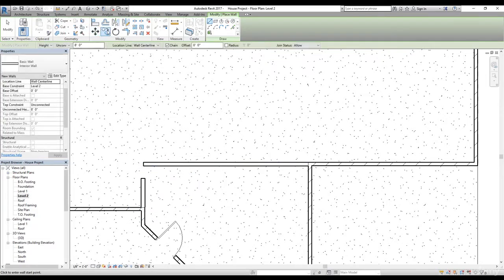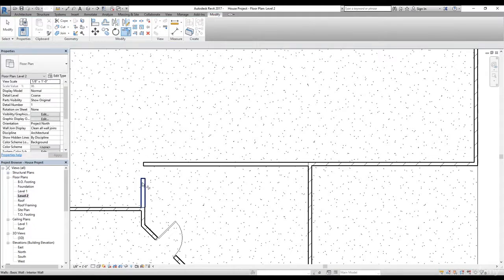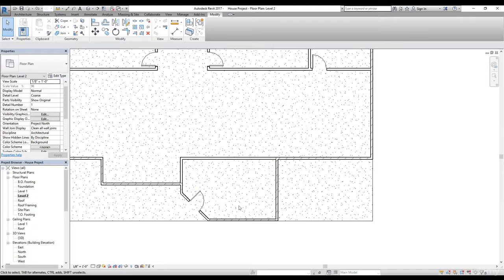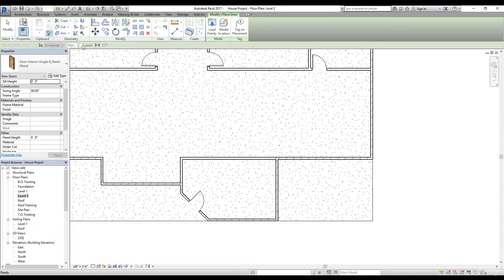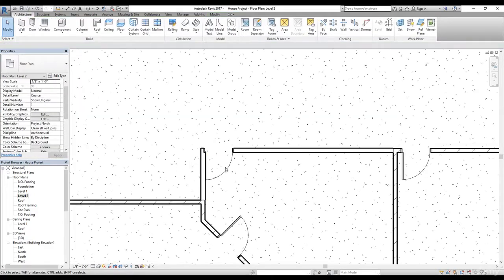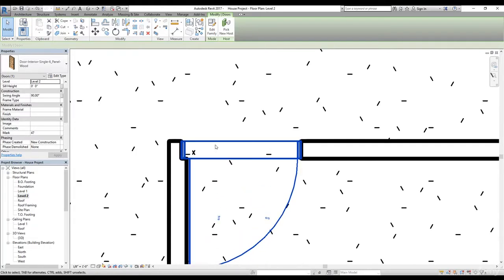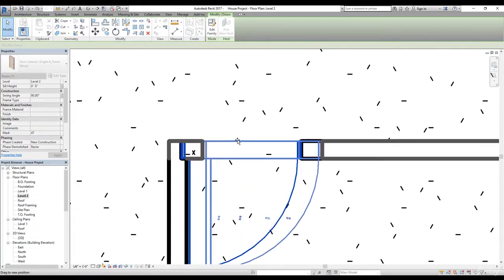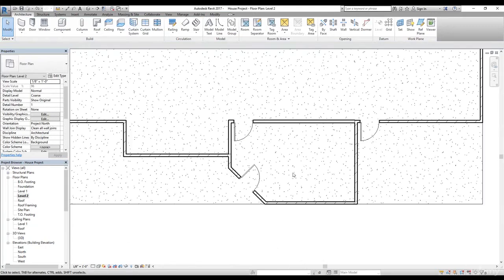Now we are going to use this trim and corner command. So let's select this wall, and that will fix that problem. Now we've got the door here. I'm gonna add another door. So let's go back to architectural tab, select this door, and we're gonna drop a door here, something like that. And then we're going to have another door which will open outside. So if someone's gonna come in outside here in the balcony, anyone can come in. Now we need to move this door a little bit to the right because it was causing a problem for the wall. Now we got these two doors done.